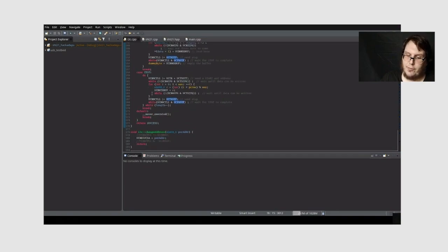This is just a little function I wrote. It's actually a linear feedback shift register, which essentially just generates all the values between 0 and 255 in a random order and sends them over and over again. This is what I use if I'm debugging. If something's going wrong, I can enter test mode and then take a look at the actual SDA and SCL lines. And then I have another function down here, change address. We pass it the address we want, and it will just write that into that register for us. So pretty simple, right?